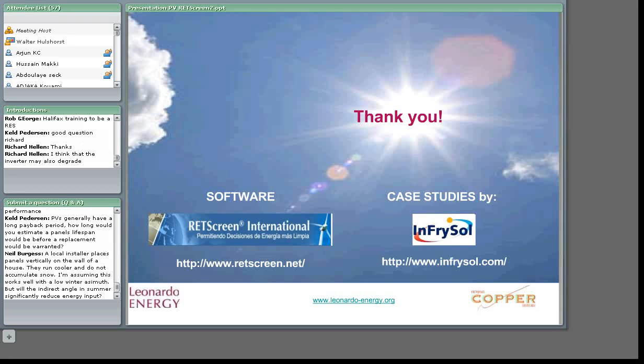Well, I think that RETScreen can be useful in this case as there's discrimination on generation by months. So by changing your angle and your orientation, you can consider the production in winter, in summer, and then optimize according to your local conditions. So basically, you should take into account whether you have a difference in winter related to summer in terms of prices, in terms of generation you are looking for.